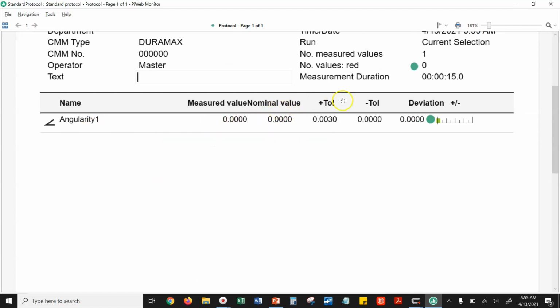And you might say, hey, that's strange. Our nominal value, it even said our nominal value should be 40. Well, when you're working with GD&T callouts, your nominal value is set in the characteristic itself. Like for parallelism, our nominal value is 0, right? Two planes have to be parallel, 0 degrees off. We didn't even have to enter that one because parallelism is really like angularity, or it's a special case of angularity where the angle is known to be 0. In perpendicularity, same deal. That's really angularity where the angle is known to be 90. And those didn't show nominal values either. So why would it be any different here?